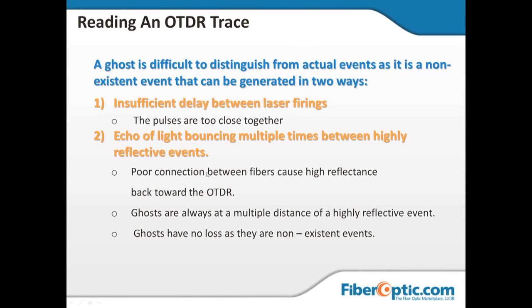What you normally have nowadays is an echo. It is simply a dirty enough connector that is causing a high enough reflection that it's bouncing back to the launch connector with enough force to make the trip again. That's it. It's an echo.